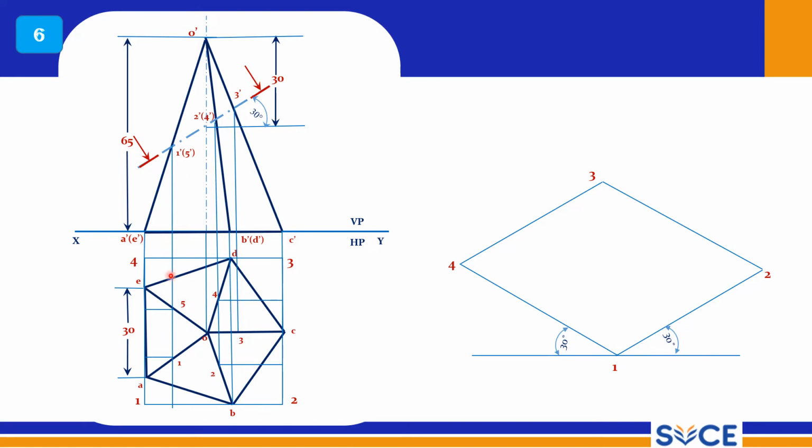These points you can project onto the top view, right? And this rectangle method you can use, and from here this height can be measured, and that height can be used to draw the point, to mark the point. So that way you can easily complete it, right?